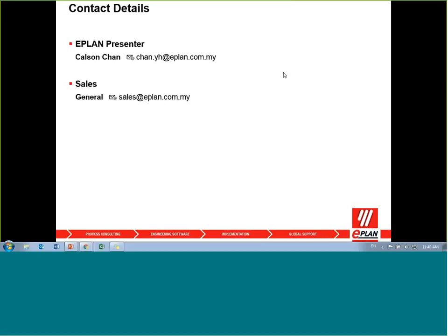Okay, so we have one question from Gil. Is it possible to copy the board frame from other projects? Okay. So basically you don't have to copy the board frame from other projects, because this board frame is already inside your working database, or what we call the system database. So basically you just need to get this board frame from your system database or your centralized database.